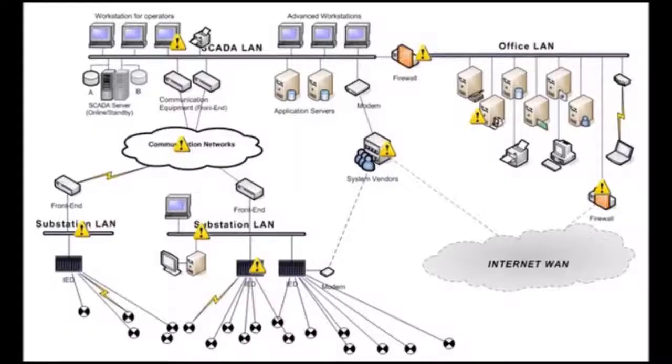Finally, the fourth generation is called Internet of Things or IoT. In the fourth generation, the infrastructure cost of the SCADA system is reduced by adopting Internet of Things technology with commercially available cloud computing. The maintenance and integration is also very easy for the fourth generation compared to the earlier SCADA systems. These SCADA systems are able to report state in real time by using horizontal scale from the cloud computing facility. Thus, more complex control algorithms can be implemented which are not practically feasible to implement on traditional PLCs.